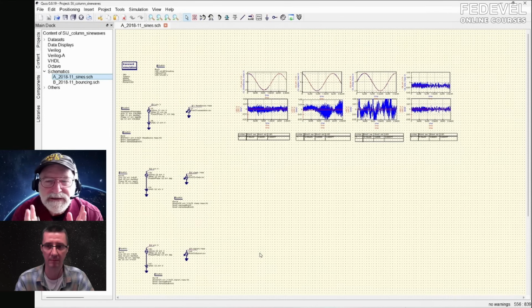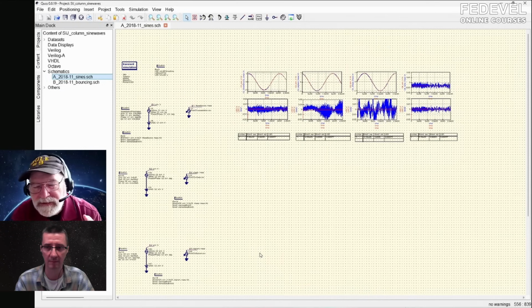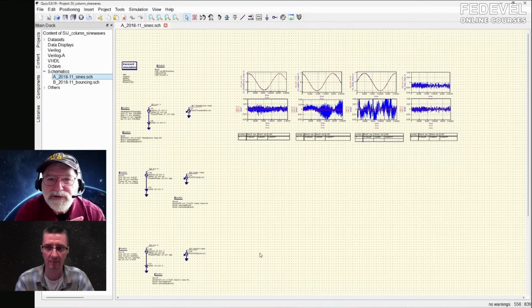And so Qucs is really a simple to use tool to help you learn and explore the behavior of transmission lines. I call simulation tools virtual prototypes. We can build a virtual prototype to explore what happens if we make the length longer, what happens if we change the rise time of the signal, or we change the driver impedance, or change the termination or the routing topology. What's going to be the impact on the signals? Sometimes it's called a digital sandbox or a digital twin of the real world.